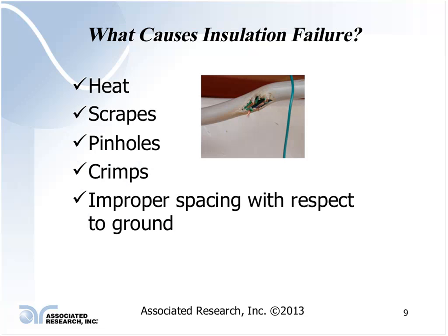What causes insulation failure? Heat can actually melt or damage the insulation. It could be damage from handling, scrapes rubbed across a rough surface. Sometimes the insulation can be damaged just due to shipping, the vibration that occurs. If a wire happens to be contacting a metal surface.